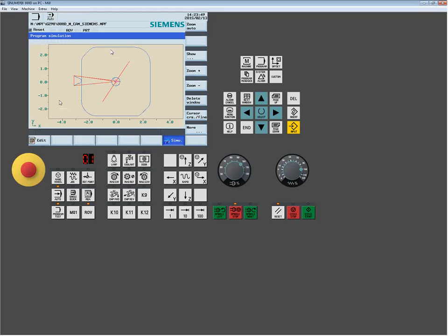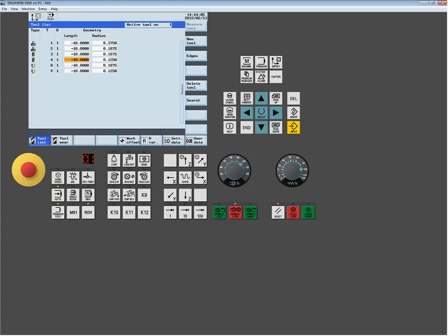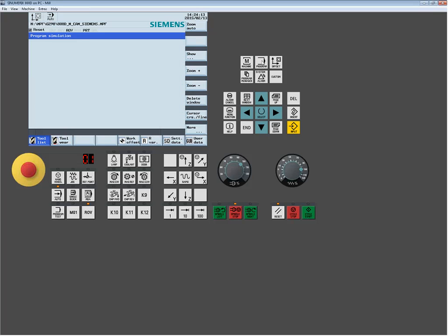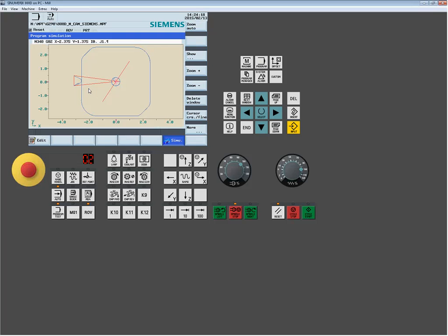So if I think it's a couple thou over or under, I could put the true value here. So let's say 0.4. I'll put a big number, for instance. And I run it. And now I see, like we saw before, I get that simple 25 thou offset. By the same token, I could come over here and put 0.350, jump over to the program, cycle start, and there you see the offset. So it's just a nice, simple little trick when dealing with programs with compensation.